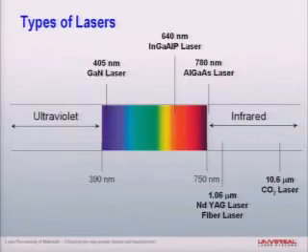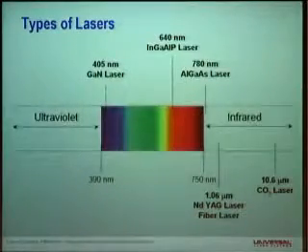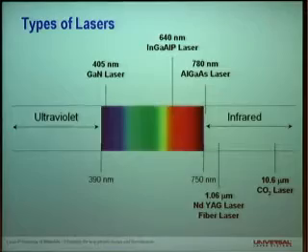Three other lasers, I'm sure you'll recognize these. These are all solid-state lasers, aluminum gallium arsenide at 780 nanometers. That's the typical laser that you'd see inside of a CD player. And then at a bit shorter wavelength, indium gallium aluminum phosphide would be the typical laser in a DVD player. Tighter packing density of data due to the shorter wavelength of the laser. And then this is Blu-ray down here, a gallium nitride laser at 405 nanometers.